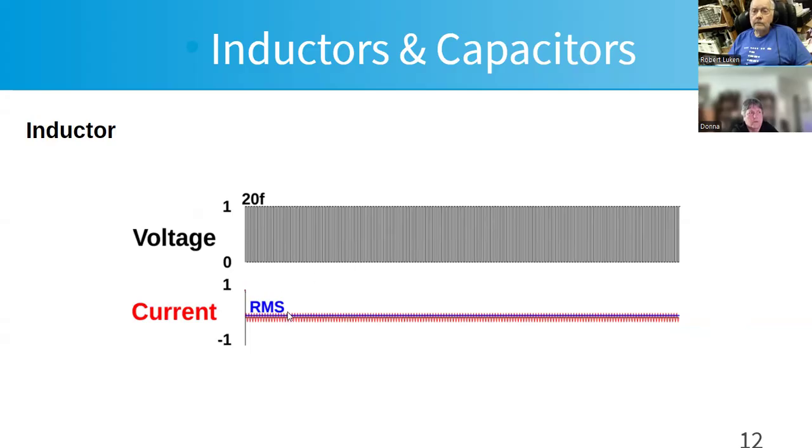And if you were to calculate what the equivalent resistance would be with the applied voltage to give you the same amount of current, you'd come up with the amount of reactance in ohms. So it's the effective resistance at that frequency for that amount of inductance. Does that make sense? Those are good graphs.